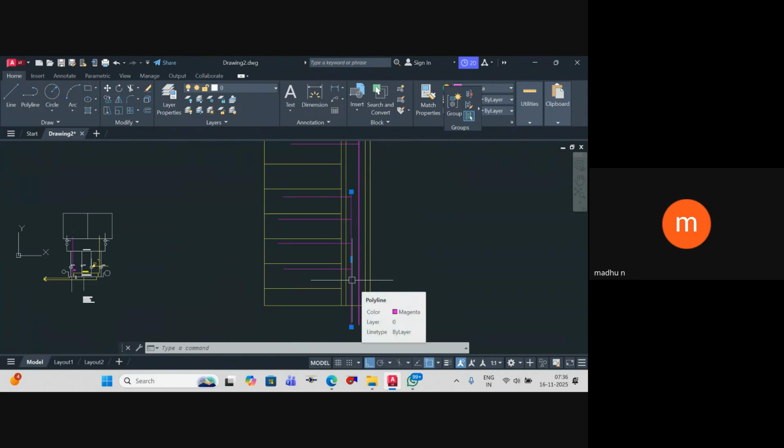You will be using two vertical pipes in a shaft for sprinkler. Two vertical pipes. If you have a 30 floor building, generally it'll never be so narrow. You'll have a very big building, a huge space. Anyway, for every 30 meters or every 45 meters, you have a shaft for your fire exit staircases. So for a few floors you use one, and for the next few floors you use another one.